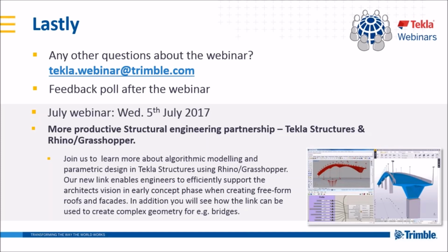We can see only the equivalent stress, the von Mises stress. And if you want to see the stresses only in one direction, for example for welds and bolts, these values are presented in the result tables. So you can see the values in the tables, not in the 3D scene.